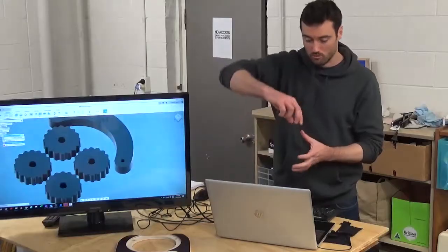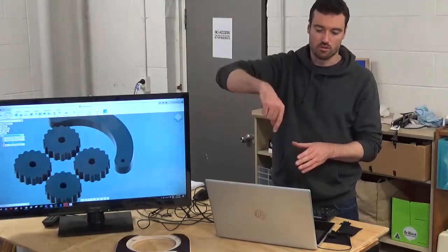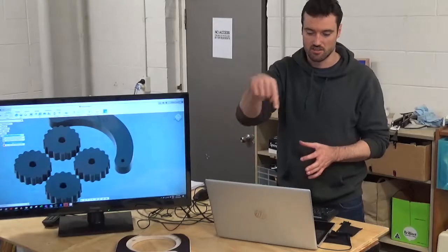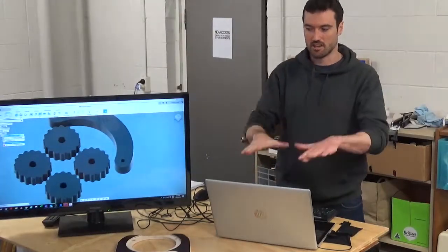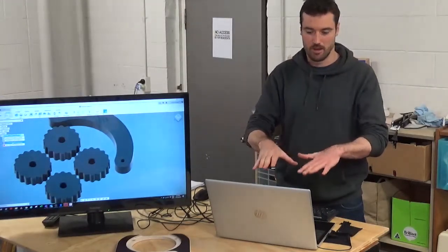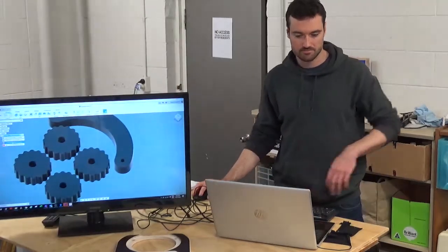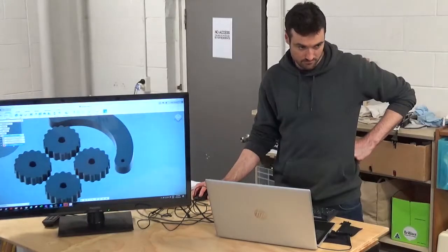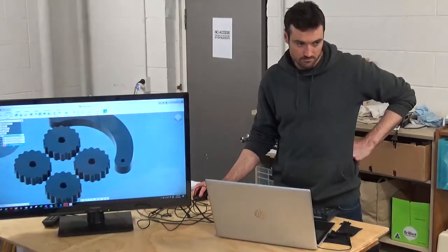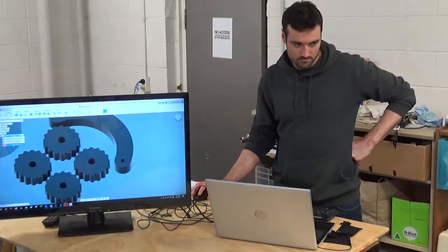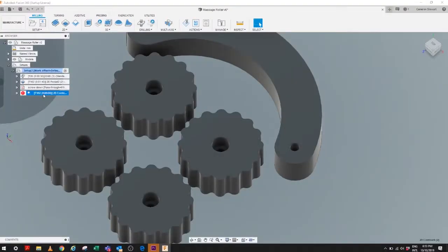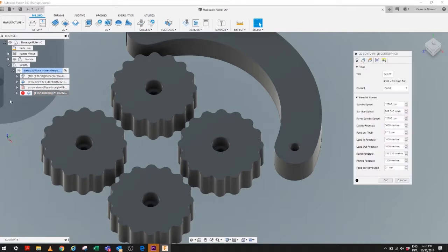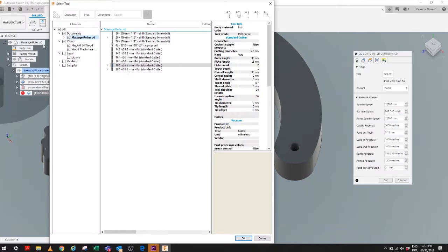So we'll fill that out, and then what we would do is put screws in each of those holes, to hold down all parts onto the table. When you're doing those pocketing or drilling, you're not really putting much pressure on the wood, it's just sitting on the table and not really moving. But when you start doing those cuts, it's actually putting sideways forces on the board. So you want to screw it down at this point.